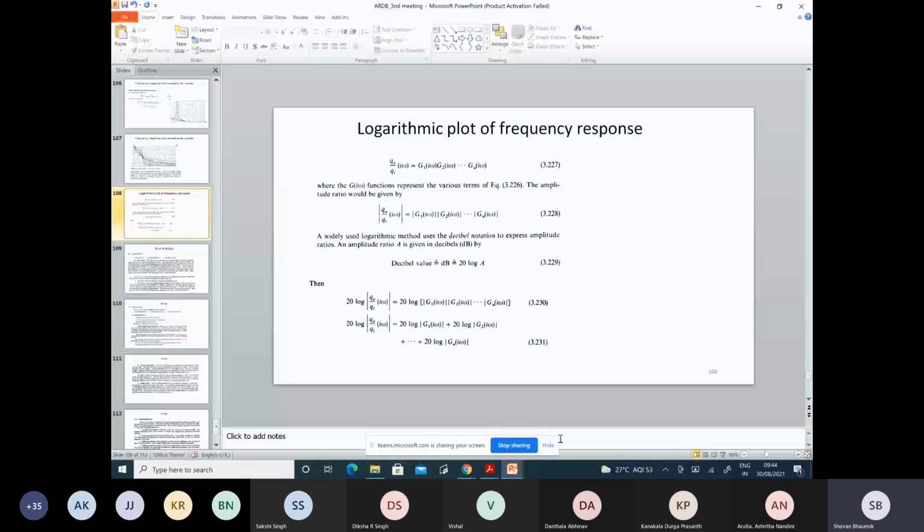We generally ask this question in different vivas and exams. Most of the students say that no, there is no utility of the phase plot in system identification. The answer is wrong. There is a huge utility. Suppose you have a single pole, and the pole might be at plus or at minus. That means at the right half of the S plane or the left half of the S plane.